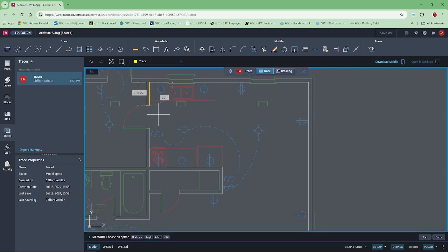In the Toolbar area, in the Draw tab, click Rectangle. Along the right side of the sink kitchen counter, draw a rectangle of the width and length that were noted on the left side of the wall, 4.5 and 2 feet 6.5 inches. Enter the width value and then use Tab to enter the length value.